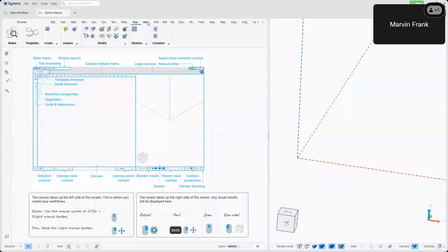And then we come to the FEA section. That's of course super important for you guys. So here you have everything that you need for modeling. For example, you already saw the solid part. We can thicken a shell mesh, or like you see also the shell mesh, the solid mesh, HyperMesh connectors that connect to the Altair software. A lot of stuff here that we use for modeling. Load steps: linear static, non-linear static, buckling and modal, and steady state heat transfer, those are the ones that are supported at the moment.